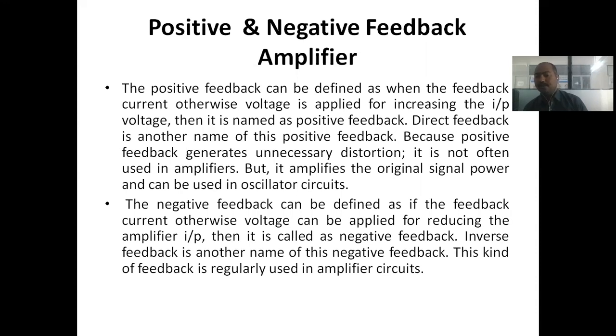This type of feedback is used in case of an amplifier. Due to the use of negative feedback, again I'm telling you, the gain of the amplifier is reduced, but it is still used in amplifiers. The reason is that although there is a decrease in the gain, it is stabilized, right? Stability is an important factor in any application, because if it gives more frequency, it is not acceptable, and if it gives less frequency, it is not required, because we need the proper required frequency. That's why we use negative feedback to stabilize the gain of your amplifier.